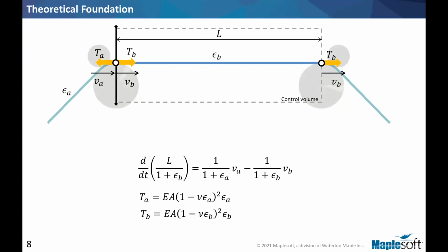Right now we have a linear elastic material included, with the option to include the change in the area cross-section due to the existence of Poisson ratio. This value is really negligible. So the default Poisson ratio is 0, but you can put any reasonable number there.